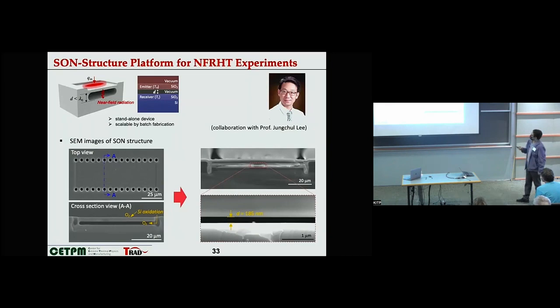We did a very primitive feasibility test. We make a silicon membrane, cavity and silicon, and we oxidized it so that the silicon changed to SiO2 membrane and substrate, some parts changed to SiO2. By oxidation, the lattice expands, so that the cavity or gap distance shrinks. So we are able to achieve around 200 nanometers without having spacers or a positioner.